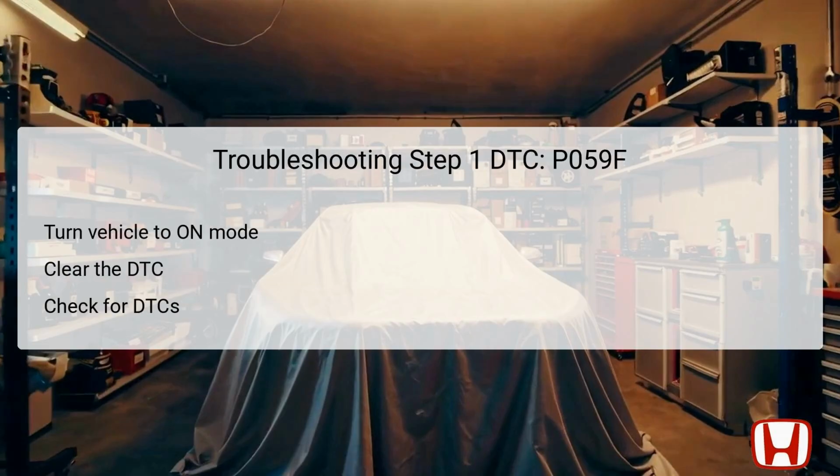The first step in troubleshooting DTC P059F involves verifying the problem through a systematic approach. Begin by turning the vehicle to the on mode, which activates the onboard diagnostic systems without starting the engine. Next, use the HDS, or Honda Diagnostic System, to clear any existing diagnostic trouble codes, DTCs. This step ensures that you're working with the most current data.